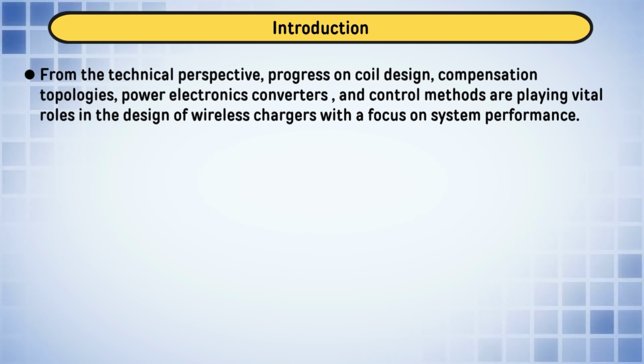this bidirectional DC-DC converter must operate in boost mode, so that the battery can push the power at the DC bus to maintain the DC bus voltage as well as inject the required power at the DC bus. So that we can operate our vehicle and we can accelerate our vehicle.